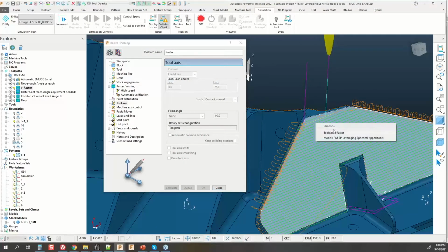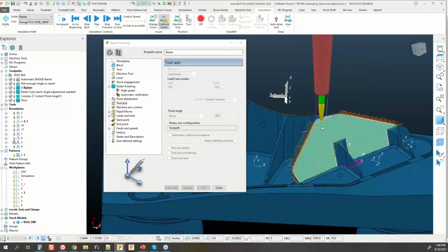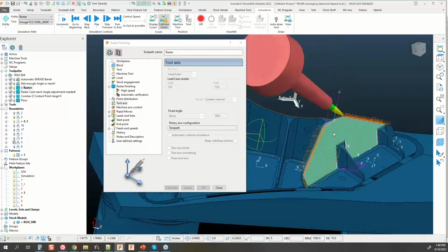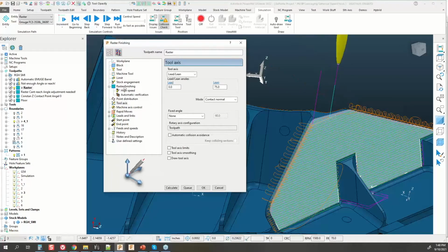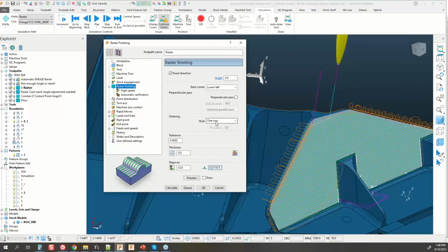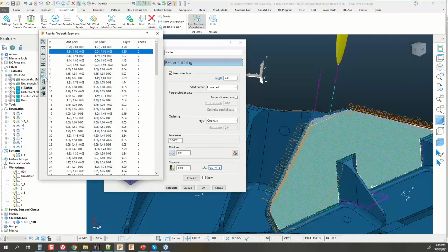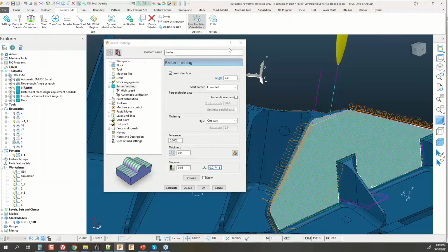And it's applying my edits to the toolpath from the previous toolpath. And there's that opposite angle. That's the undesired angle that I might want at that point. It's also wrapping around the top of the surface. But after calculating that based off of a one-way, in order to get it to move back and forth, we just simply go into a toolpath edit, and then we would, of course, use our alternate directions to flip that to be a zigzag toolpath on that surface.